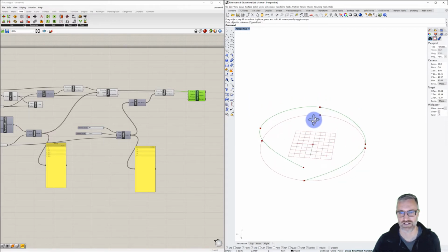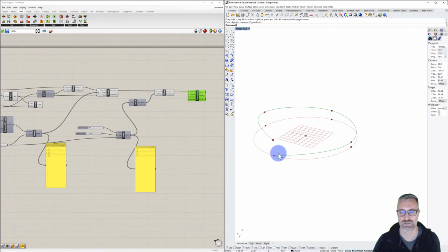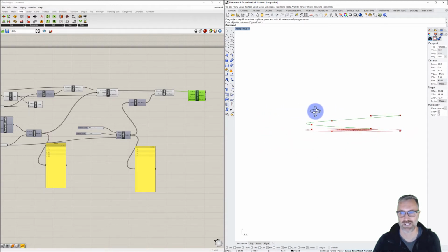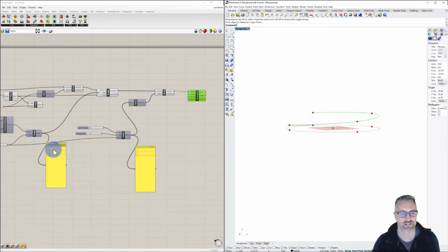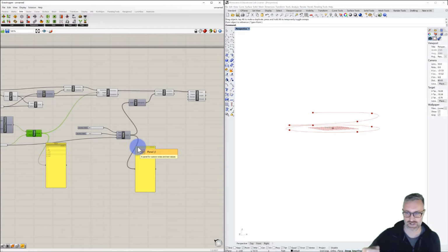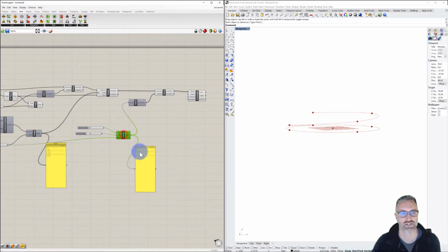And we get a curve drawn through those points. And so we can see it's starting at 1. It goes up a little bit, up a little bit, up a little bit. And actually what's happening here is that because our number of points is driven by the domain and driven by the range, and the way that we're elevating those points in Z is driven by this series, we can see that the last 2 points are actually the same. It's just duplicating. It's doing 0, 1, 2, and 3. And so this is 0, 1, 2, 3, and 3.